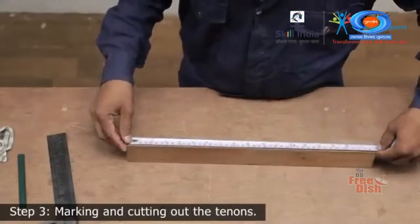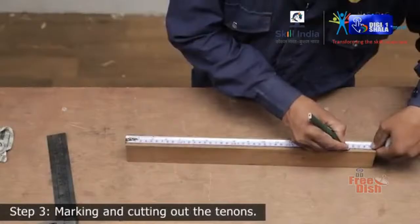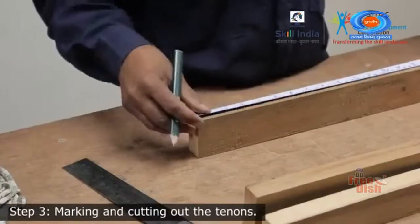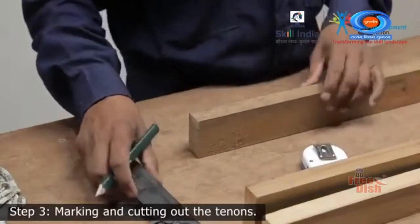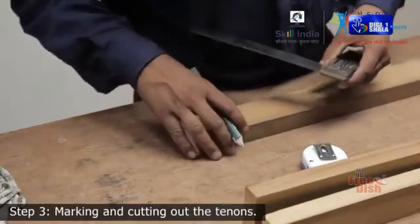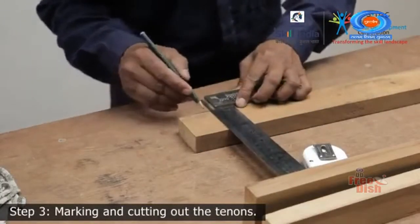Now take 1 framing piece, measure and mark the points for the length of the tenon on both the edges. With the tri-square, draw a shoulder line all around the piece. This will determine the length of the tenon.